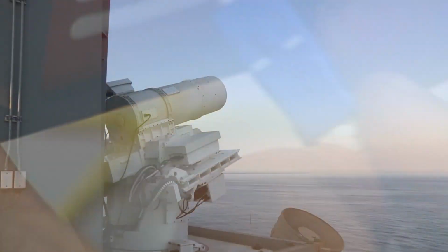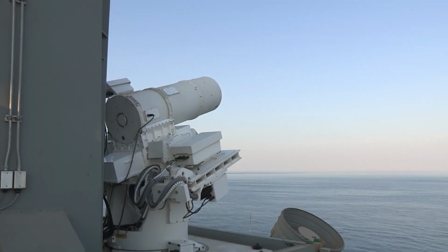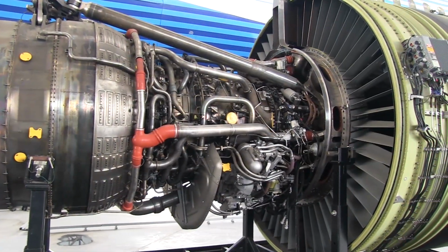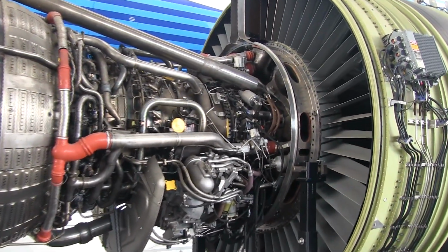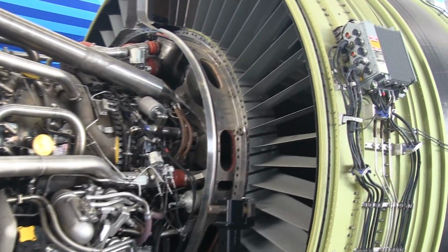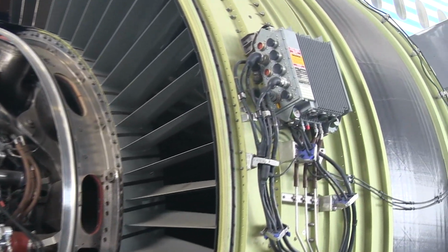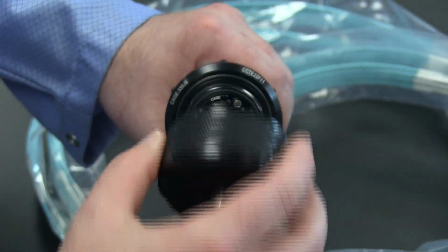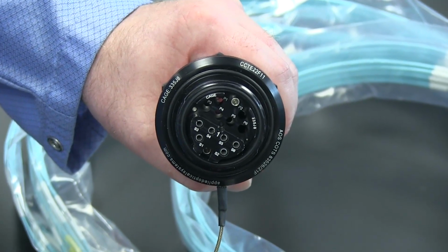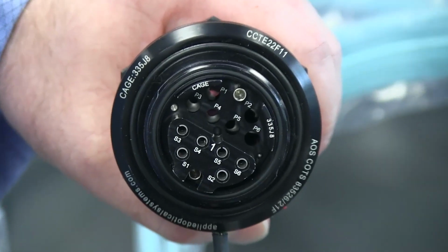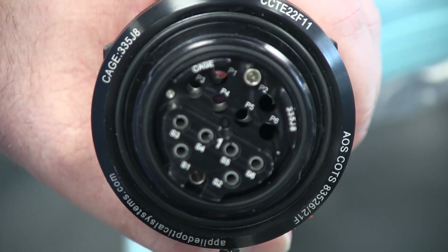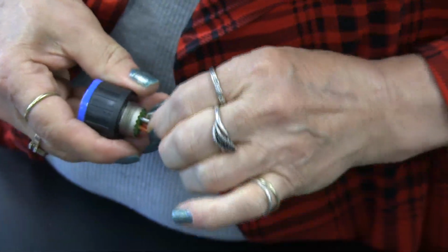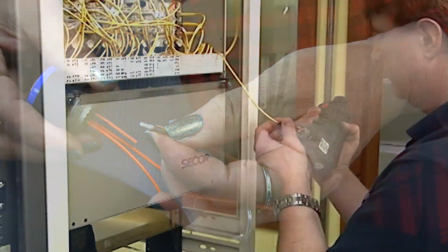In high-speed or mission-critical fiber systems, it is vital to verify the condition of connectors. How clean are they? Are they scratched or damaged in any way? It's been estimated that more than 70% of the problems found in optical connectors can be traced to dirt and contamination. In addition, because many contaminants are abrasive, mating dirty connectors can result in permanent damage to the precision optical surfaces of the termini, requiring repolishing or replacement. Handheld optical microscopes allow the technician to closely view the connector ferrule.